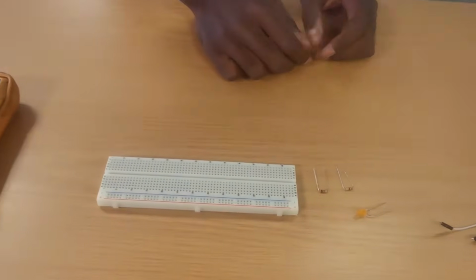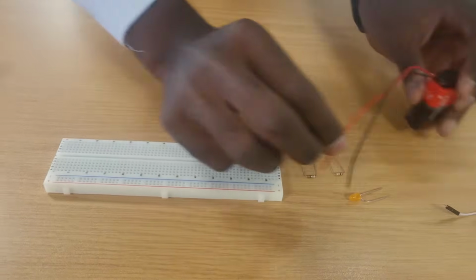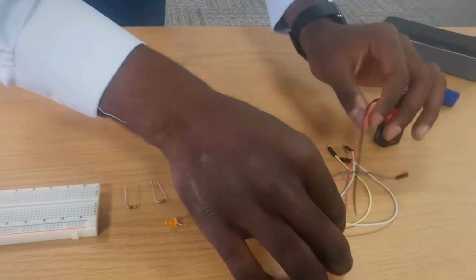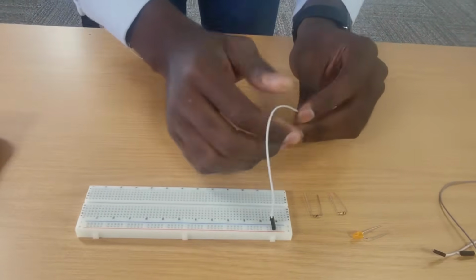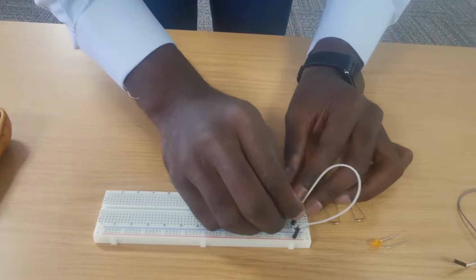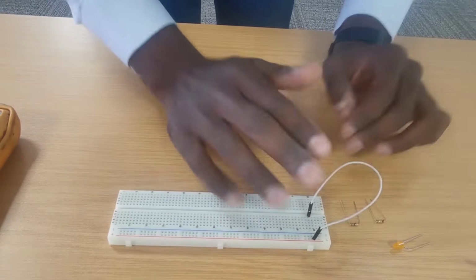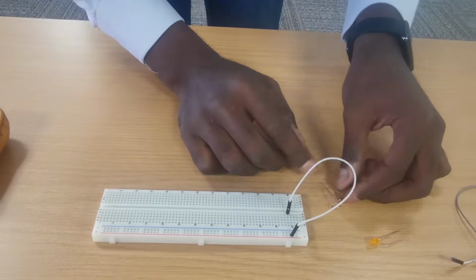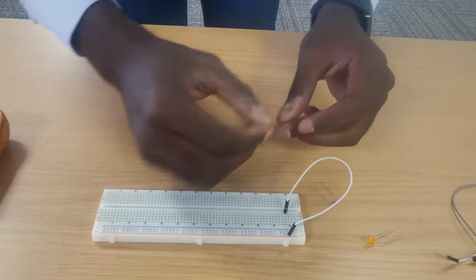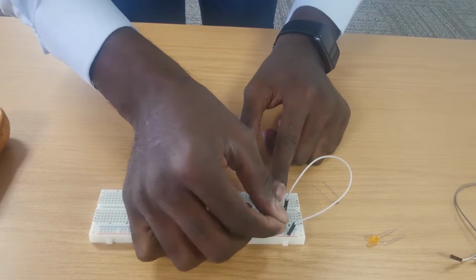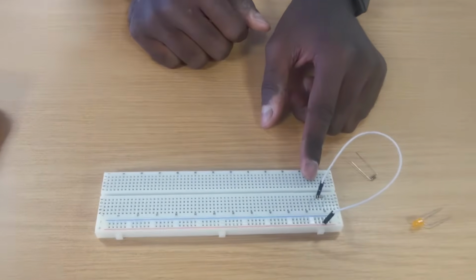So I'm going to start off by connecting my battery to the positive and to the negative. Actually, let's maybe wait with that. We leave that till the end. So I'm going to connect a positive output, my output of the positive, to one of my vertical lines. Okay, maybe take a bit lower there. And then from there, I'm going to connect my 10 kilo ohm resistor. Okay, so there's my 10 kilo ohm resistor. I can connect it anywhere in this line. That's it, right? So I'm going to connect it between there and there. So my 10 kilo ohm resistor is connected now.